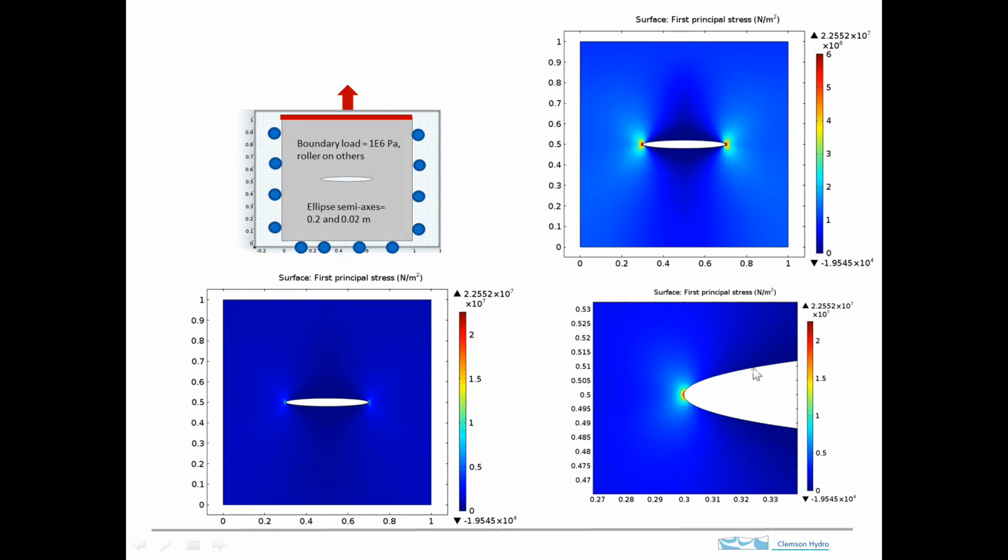And indeed, this is the way that fractures are represented in materials, and the propagation of fractures is simulated by calculating the stresses and evaluating whether the stresses have exceeded a failure criterion. And if they have, then you say that the failure occurs right here, and the bonds break, and this fracture propagates out. We won't do that. That's more of an advanced analysis, but that is how fracture propagation is analyzed.